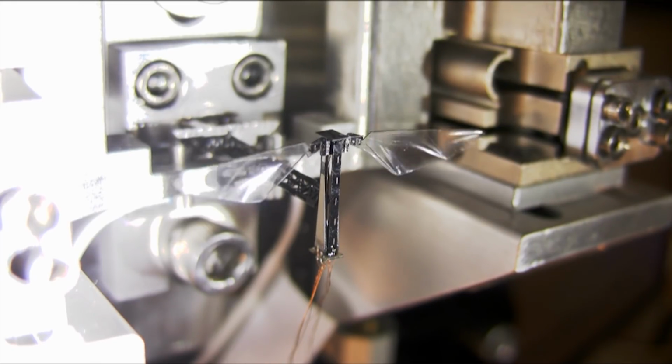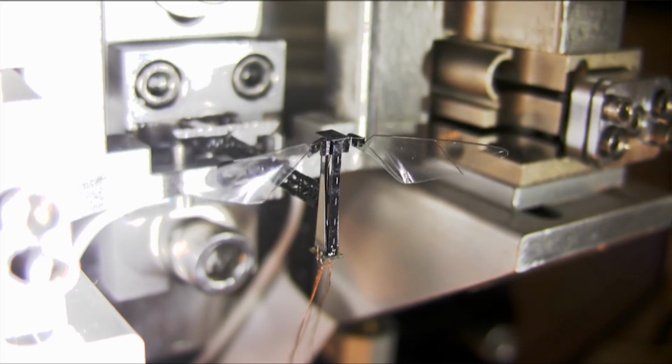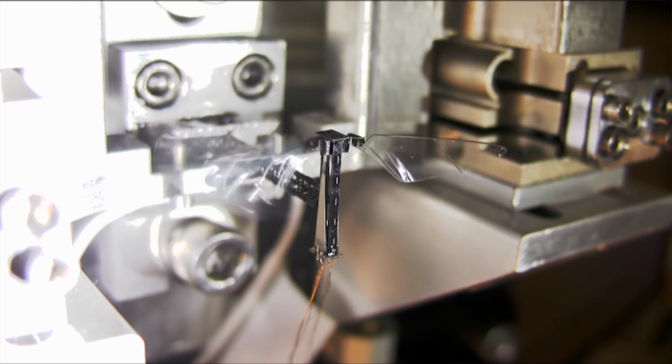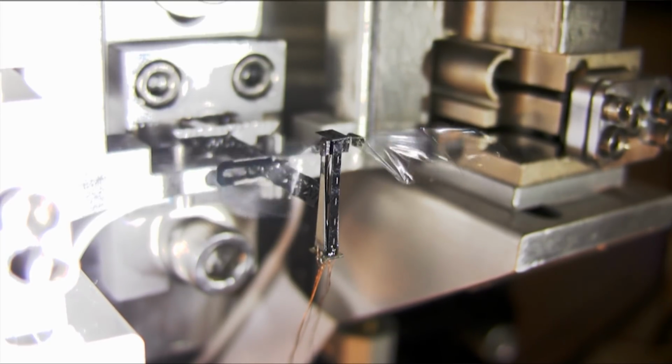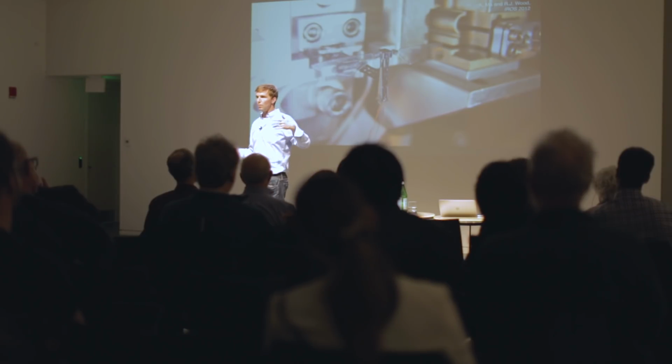The way that this works is I flap these things, and it's basically like an amplitude modulation scheme with cross product with the way a helicopter flies. I flap these things at resonance, so I don't change the frequency of operation, I just create bilaterally asymmetric amplitude changes. If I have a fixed frequency and change the amplitude, I'm changing the velocity of the wing. The lift force generated goes as velocity squared, roughly.